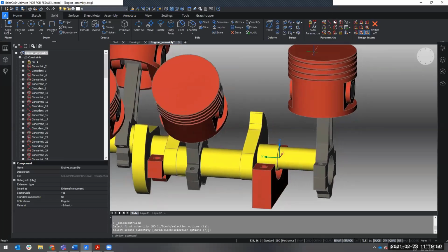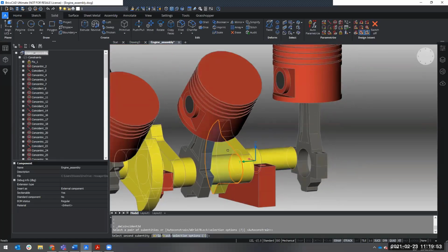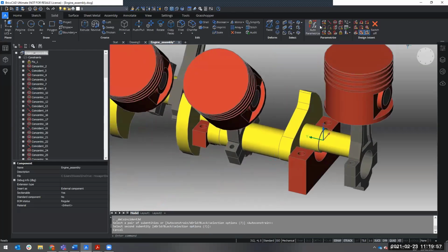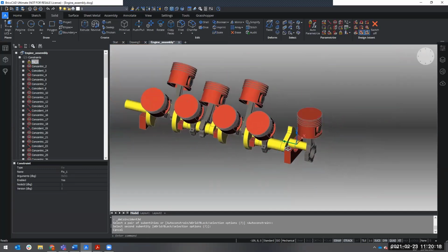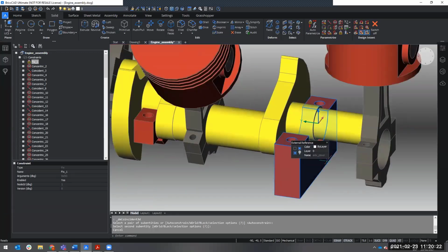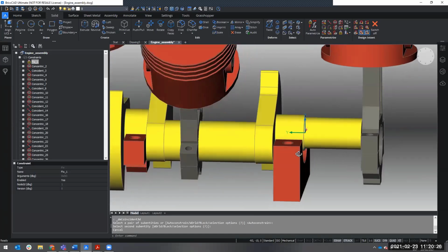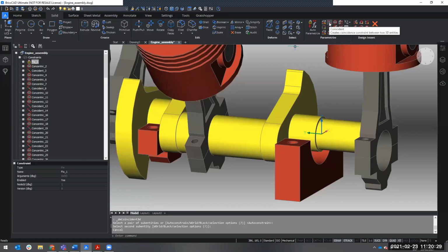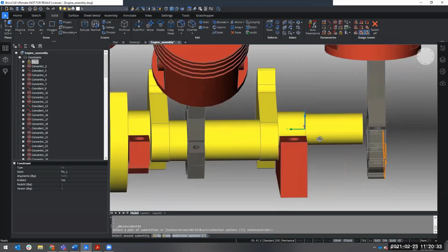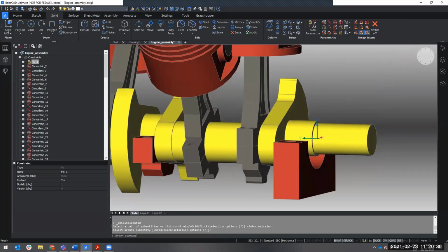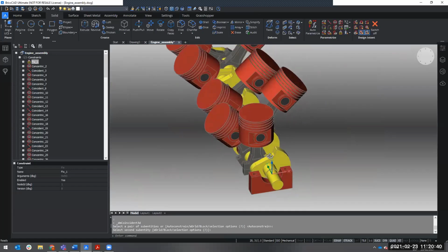And then we still need to do a coincidence again, this time from this face, from the one that doesn't stay in place. Well, if something in this assembly is fixed, it actually doesn't matter, because that will prevail over the order in which you choose things. Since this assembly is fixed by a certain plane, I think, it doesn't matter too much, so you can be quite intuitive about it. So you press coincidence between this face and this face, and then it moves there, but you see that it's not rotated yet in the correct way.